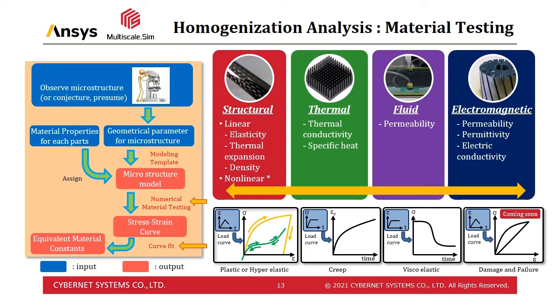As I mentioned at the beginning of the presentation, damage behavior is not negligible in some composite materials. Damages can be seen when the slope of the graph is different between initial loading point and unloading point. In other words, elastic constants are changed with increasing external load. We are actively developing anisotropic material constitutive law to expand the scope of multiscale analysis. We can confidently say that not so many tools can provide functions ranging from virtual material testing to curve fitting for such a wide range of problems.